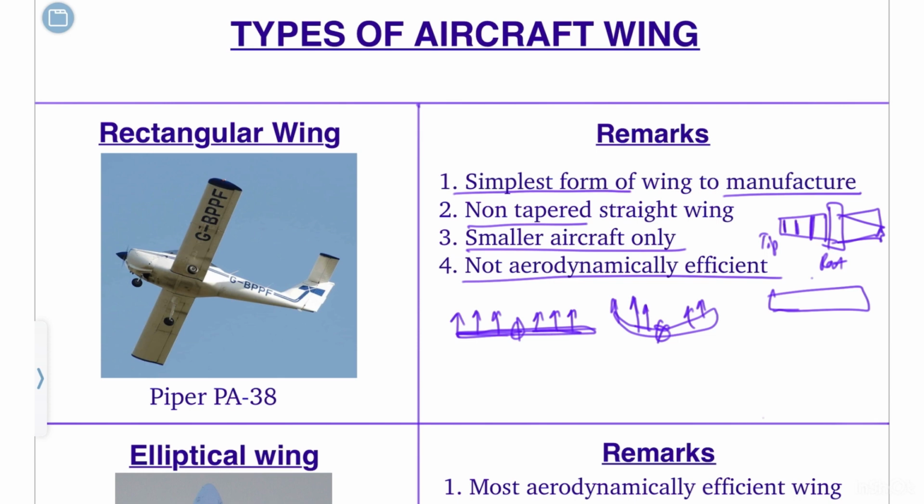Second, these aircraft cannot go very fast because of the generation of shock waves as the aircraft reaches the transonic range. Subsonic is the range up to 0.8 Mach. Mach is the speed unit. From 0.8 to 1.2 Mach is the transonic zone, where shock waves start to generate, where the sonic boom and everything happens, and above 1.2 Mach is the supersonic range.